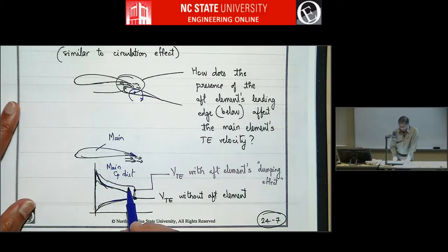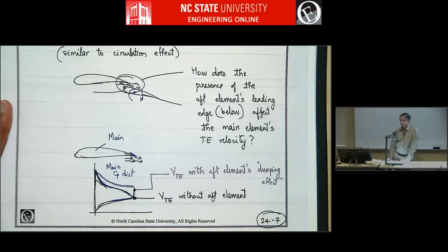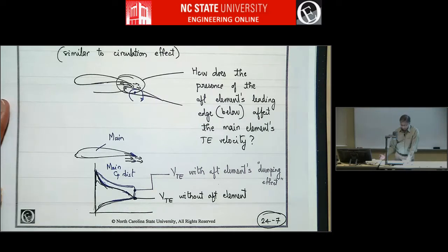And so you get a higher V trailing edge. And because you get a higher V trailing edge, if you have a suction peak here, without the flap, it would have had to come all the way down here, so the big adverse pressure gradient. With the flap, because the V trailing edge moves up, the amount of adverse pressure gradient is decreased. So separation on the main element is postponed, and so the main element is able to generate more lift before it starts stalling.